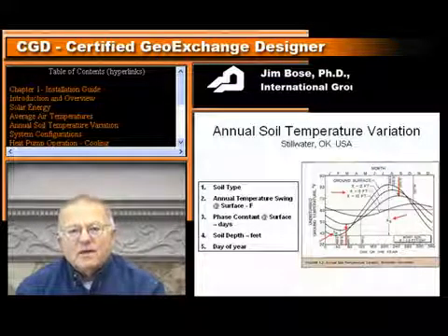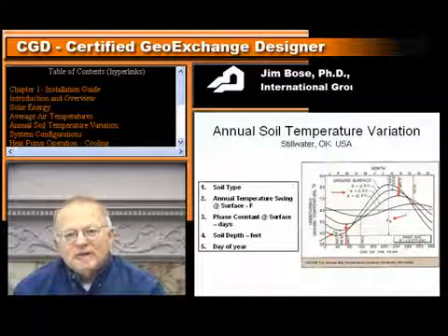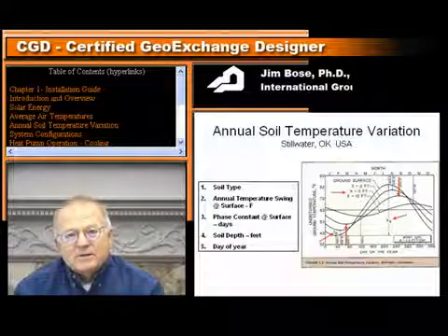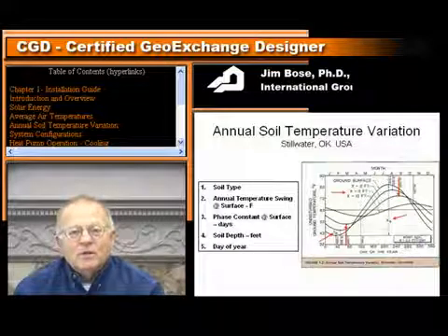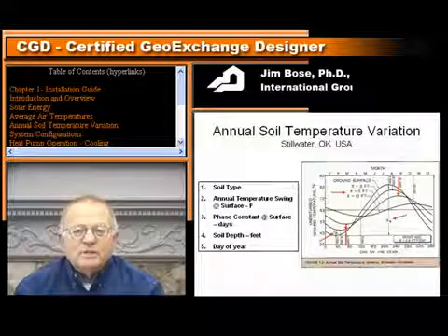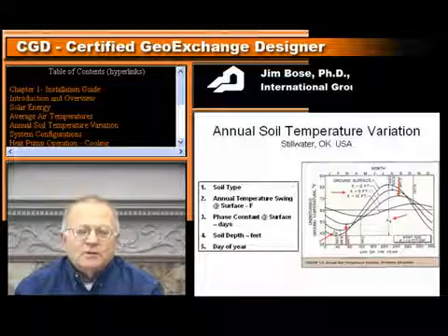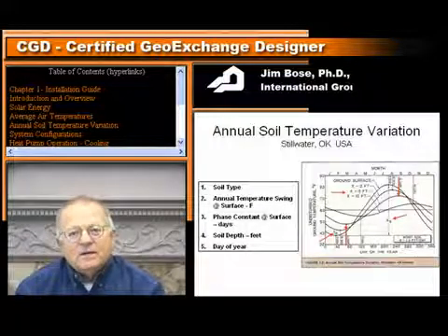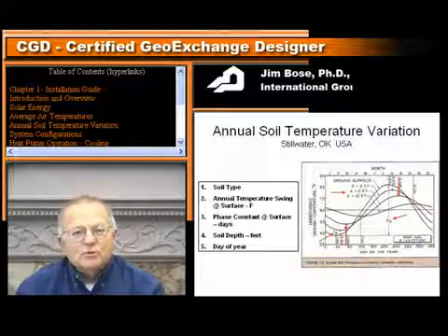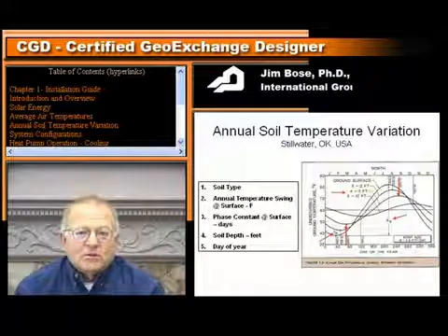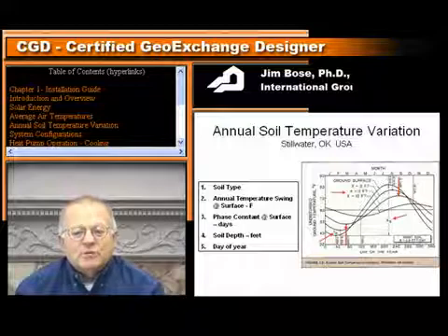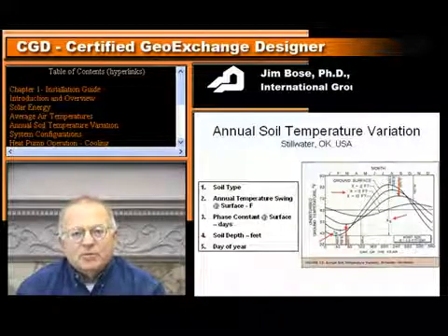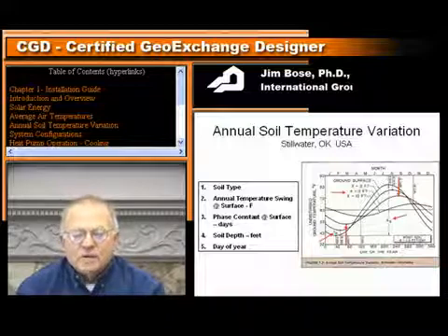We call that the ground surface. The ground surface is not a thermocouple or a measuring device laying at the surface of the earth, but a couple inches below the top of the ground, because originally most of the soil temperature data that was recorded was for farmers, so that they had some idea of when the soil temperature was appropriate for planting. So when we talk about the ground surface temperature, we're talking about somewhere around 2 to 3 inches below the ground surface.